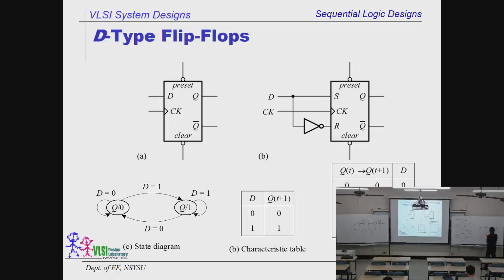So after power is on, everything with memory features must enter a so-called initial state. Here the flip-flop is the same. The clear or the reset means that you got to be 0. If it's a preset, that means it is written to 1. Either way is acceptable.